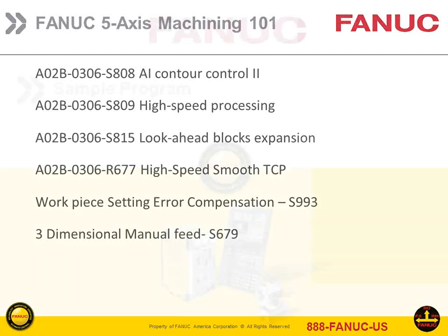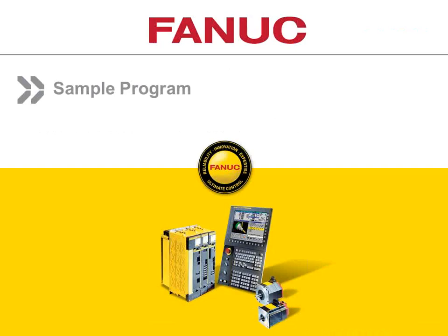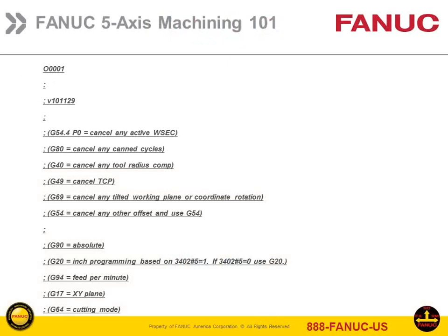Then, I want to show you a sample program, because as I've traveled around and talked to different end users, people are always asking me what the format of a program in 5-axis is. This is a sample program. Regarding the sequence of events that you need to put in a program, typically at the beginning you're going to have your standard startup modes where you want to cancel any modes that you might have turned on during the program.